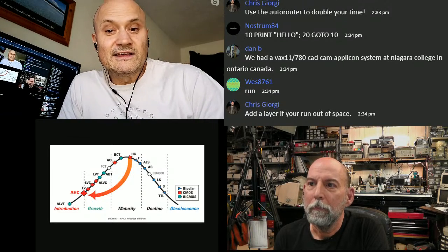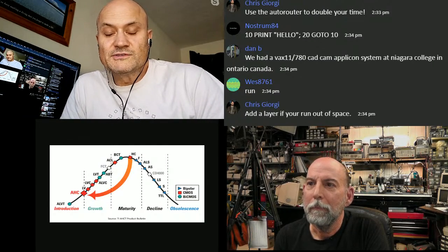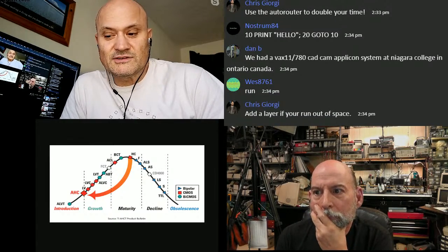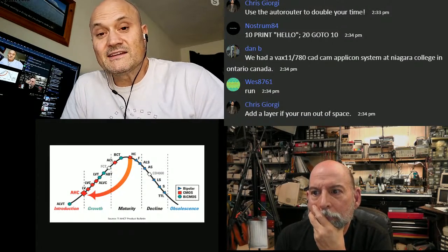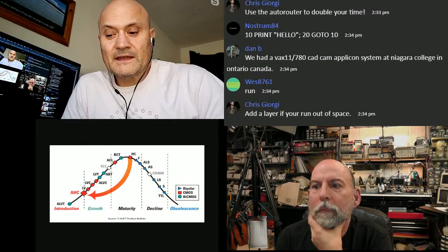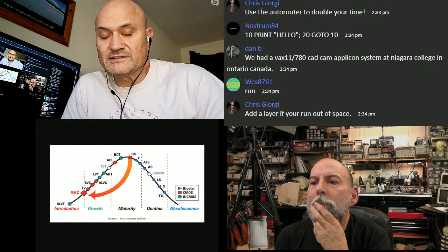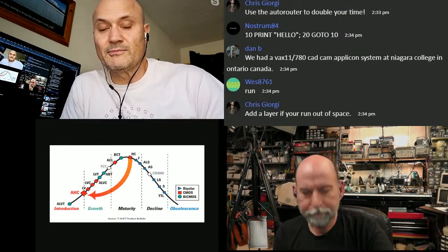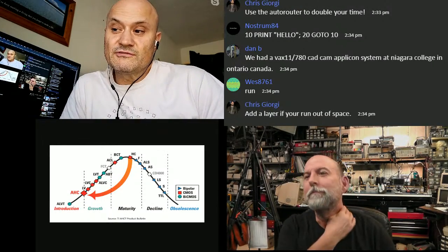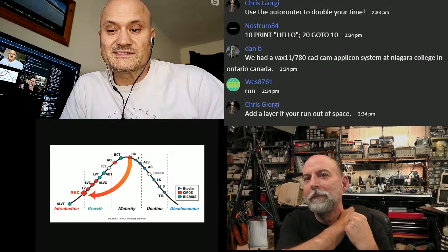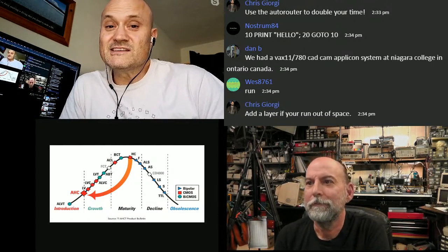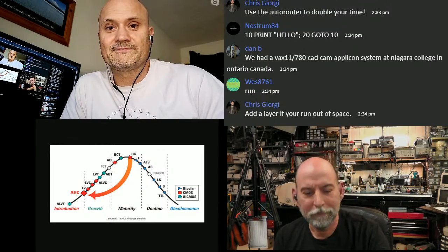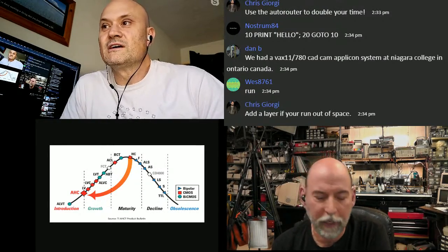But a practical engineer would use automation, at least in part, because you need to do what you can to get the job done faster. And using auto routers can give you an idea of how solvable something is, even just as an experiment. Even if you intend to route it all by hand, you can run an auto router on it with your design rules to see, is this an unrealistic ask, or do I need to modify the layer stack? Right, which somebody mentioned also, yeah.